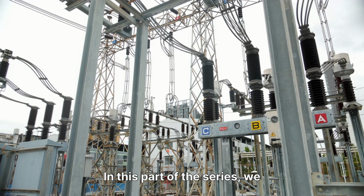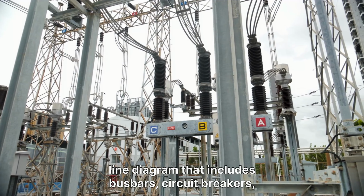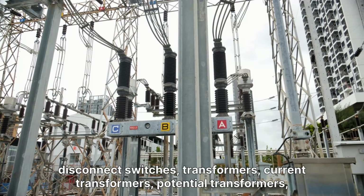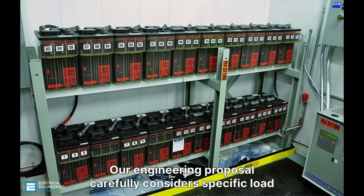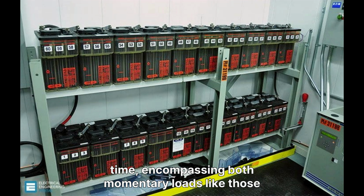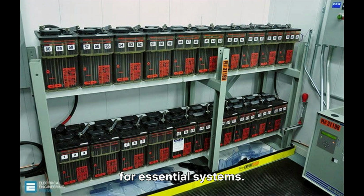In this part of the series, we will delve into a detailed practical example for battery sizing, using a substation single-line diagram that includes bus bars, circuit breakers, disconnect switches, transformers, current transformers, potential transformers, and protection relays as the foundational basis for our calculations. Our engineering proposal carefully considers specific load conditions that occur during the critical tripping time, encompassing both momentary loads like those from tripping operations and continuous loads that persist throughout the event, ensuring reliable power for essential systems.